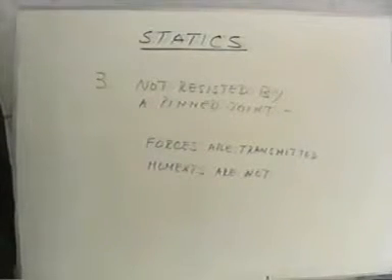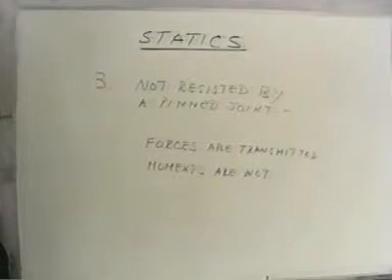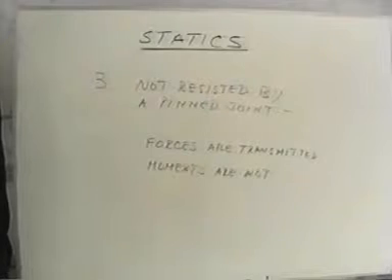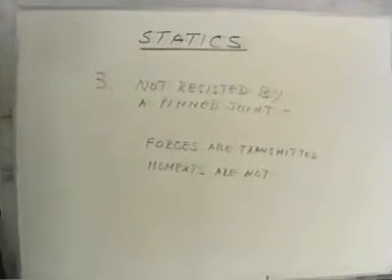The next question asks, which type of load is not resisted by a pinned joint? Well, with a pinned joint, forces are supported. Forces are transmitted, but not moments. Moments are not transmitted. Moments are not supported by a pinned joint.